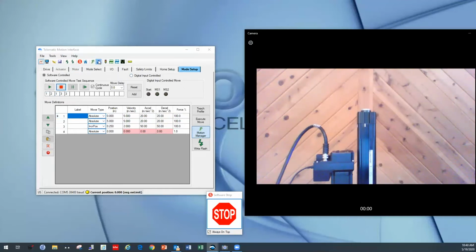So if you look up in the top here, there's a bunch of different icons that are used throughout the software, and it's available there. First of all, notice that this is a write to flash. That's going to write this program to the drive's flash memory in the back of the drive there. So it's writing it in. You also have these features restore and write on the toolbar up on the top. So if you write the settings in and operate it, then you can restore later. You could also save it, open it from a file, and go through those features.